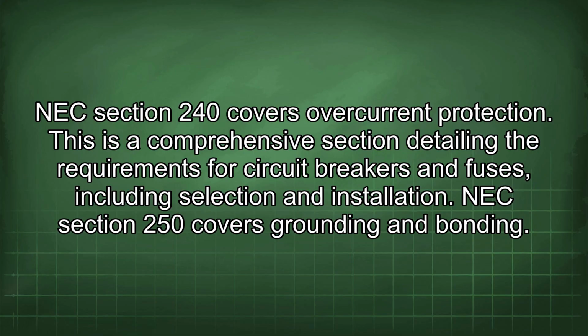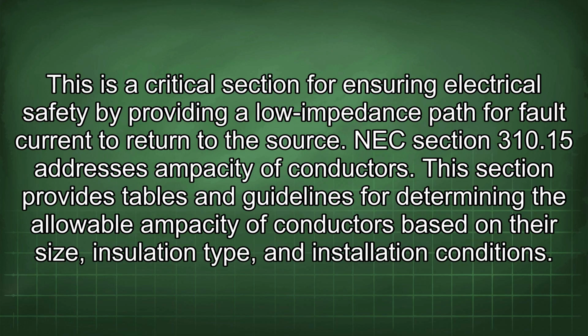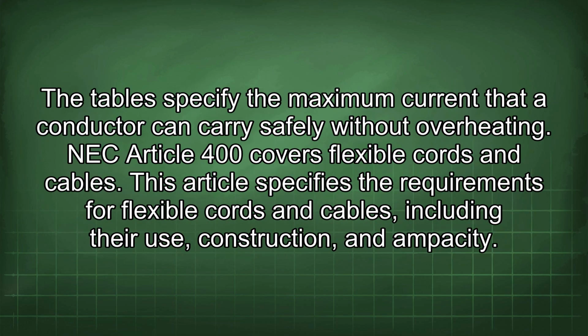NEC Section 250 covers grounding and bonding. This is a critical section for ensuring electrical safety by providing a low impedance path for fault current to return to the source. NEC Section 310.15 addresses ampacity of conductors. This section provides tables and guidelines for determining the allowable ampacity of conductors based on their size, insulation type, and installation conditions. The tables specify the maximum current that a conductor can carry safely without overheating.